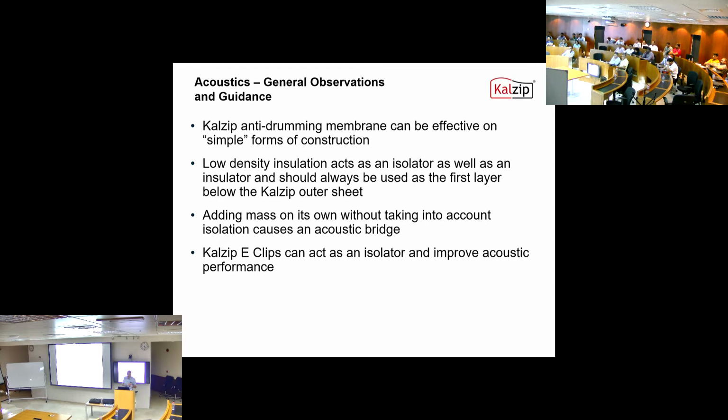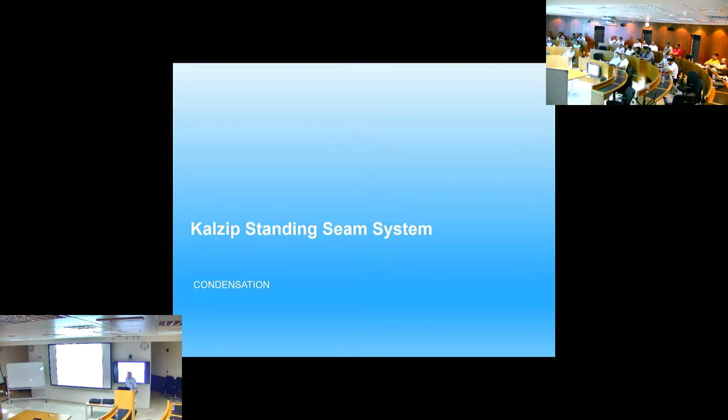And just adding mass on its own can cause an acoustic bridge, so it doesn't have any benefit from acoustic sound reduction. And as I showed you, the E-clips are beneficial from sound reduction points of view. Any questions there?